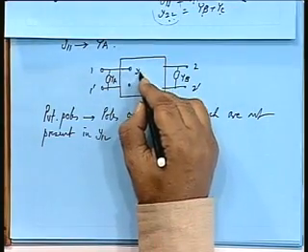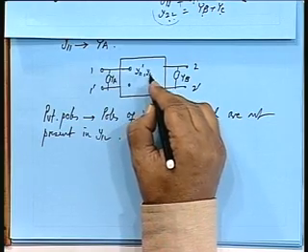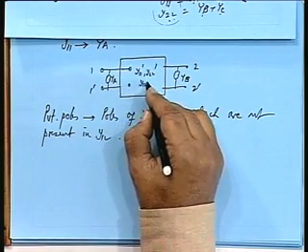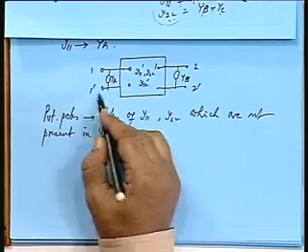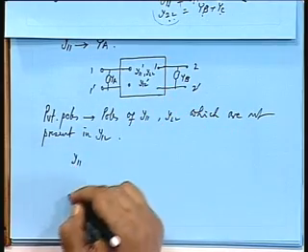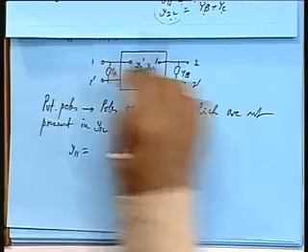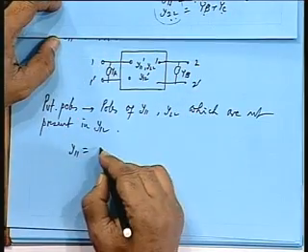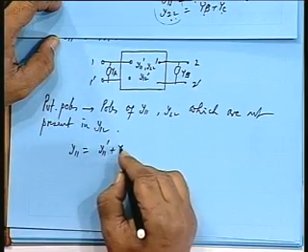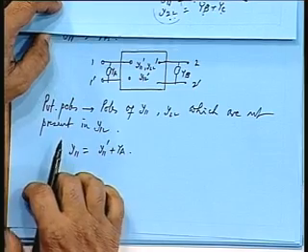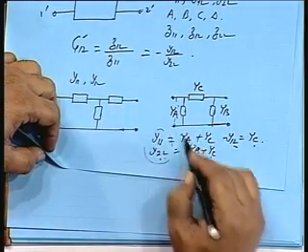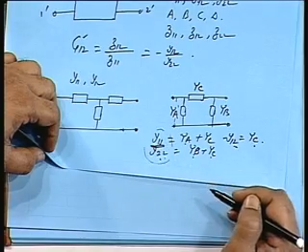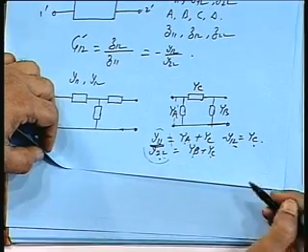Okay. So, if I have a network which is having Y11 dashed, Y22 dashed and Y12 dashed as the parameters, then Y11 as seen from this side will be Y11 dashed plus YA. Any addition of an admittance here will be adding to this value only, is it not?